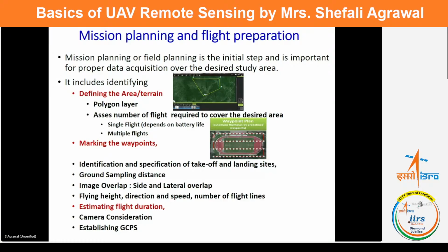And generally, the data should be collected at very low sun angles, right? So that you have good light conditions. And ensure that you also define the flight time durations depending on your data area, the spatial resolution, and the battery power.